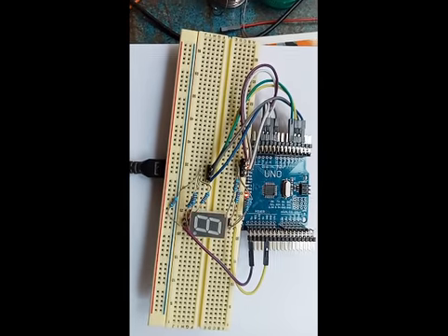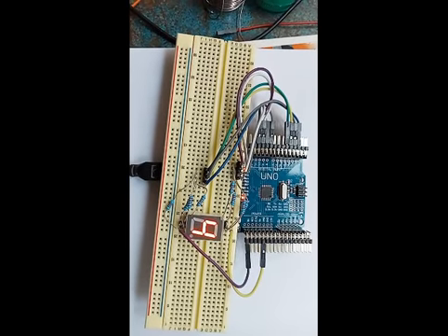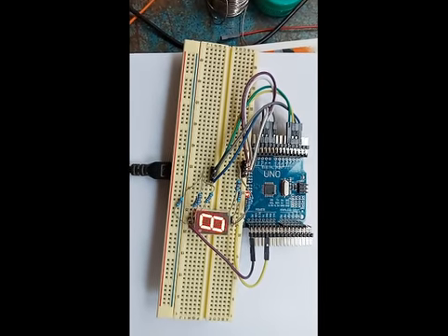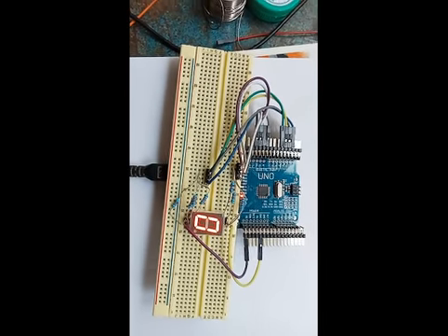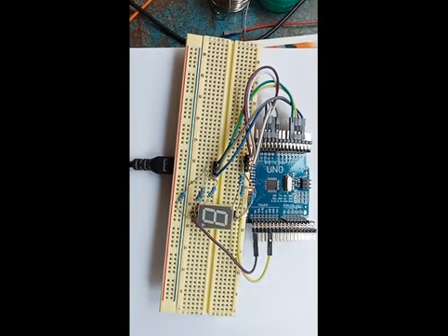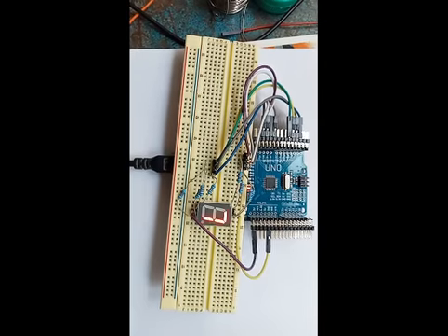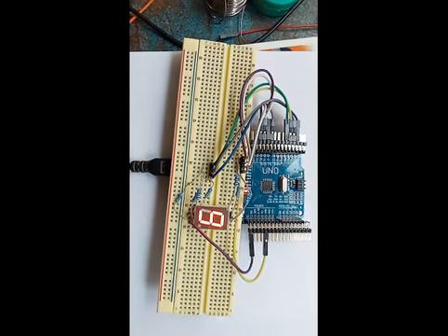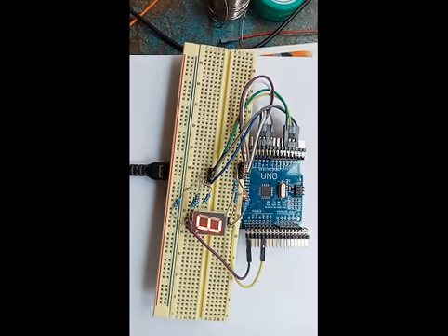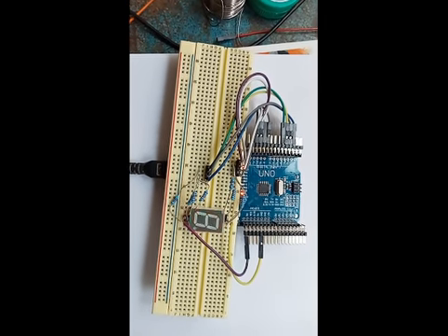The only thing is, while connecting, be careful you don't short these pins, because the segment LEDs might get damaged if you give more current. One of the important considerations you have to see is to have resistors of sufficient values so that the display comes up properly. We have used 330 ohms, as we mentioned. You can try around with different resistors.